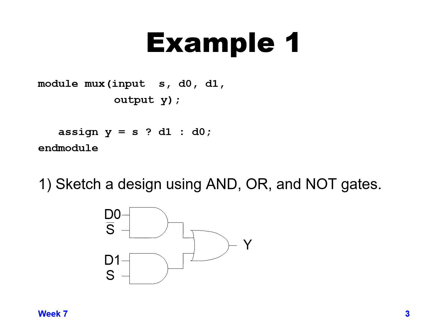So the way those two ANDs are working is if S is true, then the value of D1 goes through the AND gate, because if D1 is 1, 1 goes out, D1 is 0, 0 goes out. And the same thing with the other AND gate if S is not true. And then we take the resultant value of those two AND gates and OR them together, and that gives us the function above.